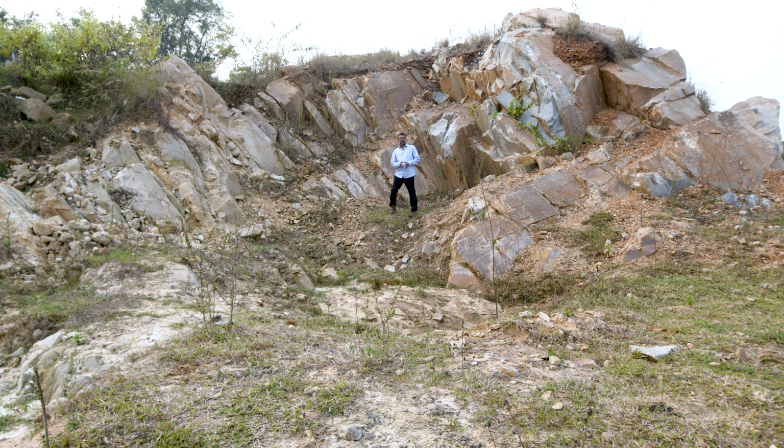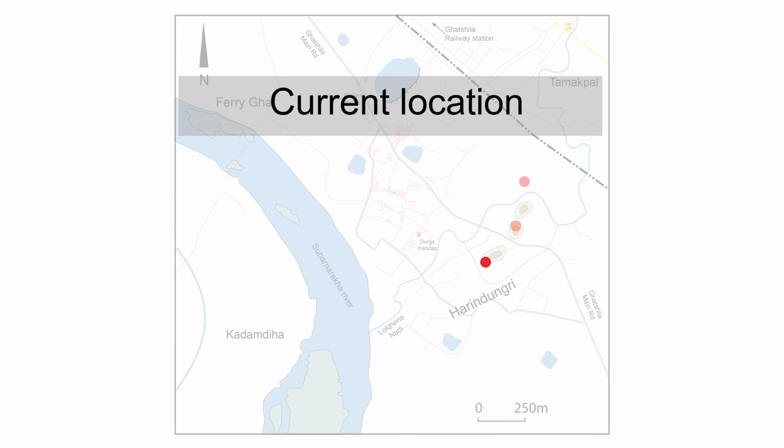Yeah, so we are following the youngest and thickest quartzite band, and we are measuring the dip and strike of the bed of this particular thickest quartzite band. So, we measured this Chitrakoot hillock, and then we have measured on the other side of the road, and now we have crossed the road, we have crossed a little canal. In front of me, this particular quartzite band has a little offset, we will see it on the map, and here we will again take the measurement.